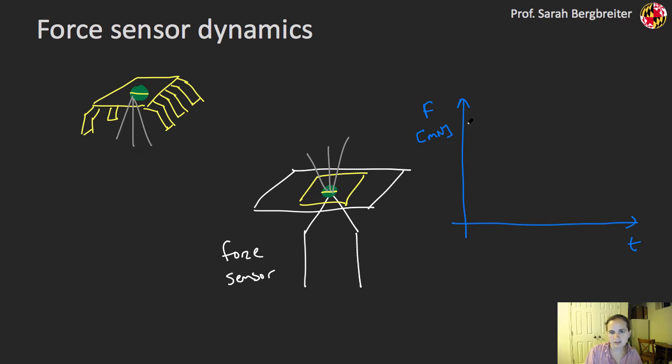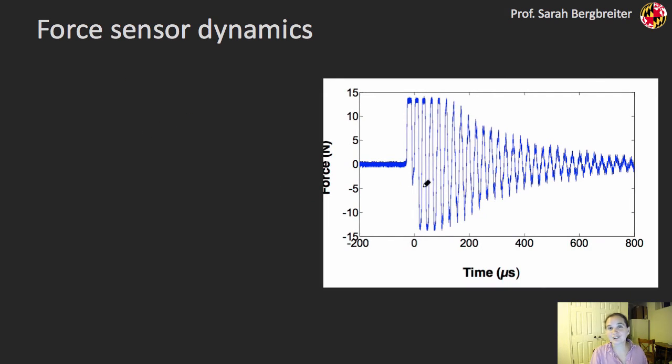And our expectation is that if we tried to measure that force, we'd get some kind of signal that might look like this, and the duration of that signal might be on the order of a millisecond, maybe less than that. We'd get a peak in the order of a couple hundred millinewtons, for example. And that was our expectation for what we might get out of these force sensor experiments. Now what we actually got was something that looks like this, and the duration was about what we expected, but we got all this crazy ringing going on here.